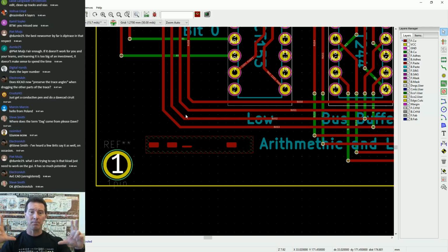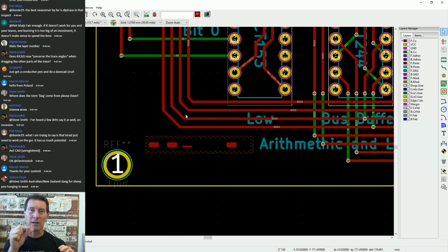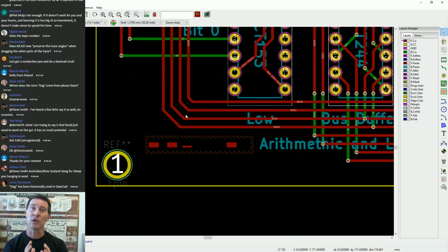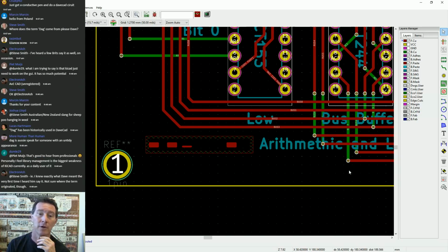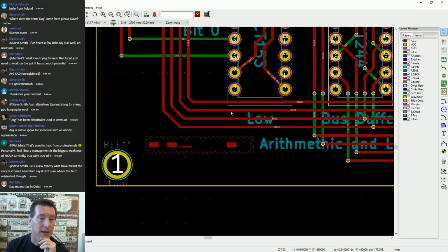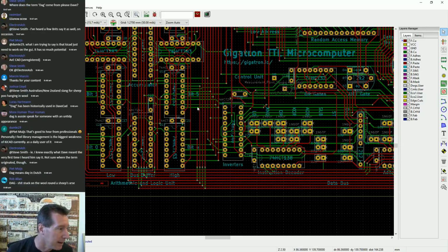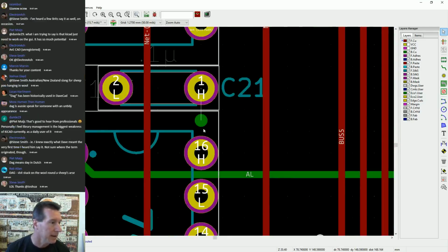Especially if you've got a large, complex board and everything's really dense, really thin traces, really fine pitched stuff that needs really good alignment, big 2000 pin BGAs that need real critical alignment on the solder mask and all sorts of things, then a test coupon is absolutely vital. So on a professional board, you would do that. So anyway, there's another one. We got one.